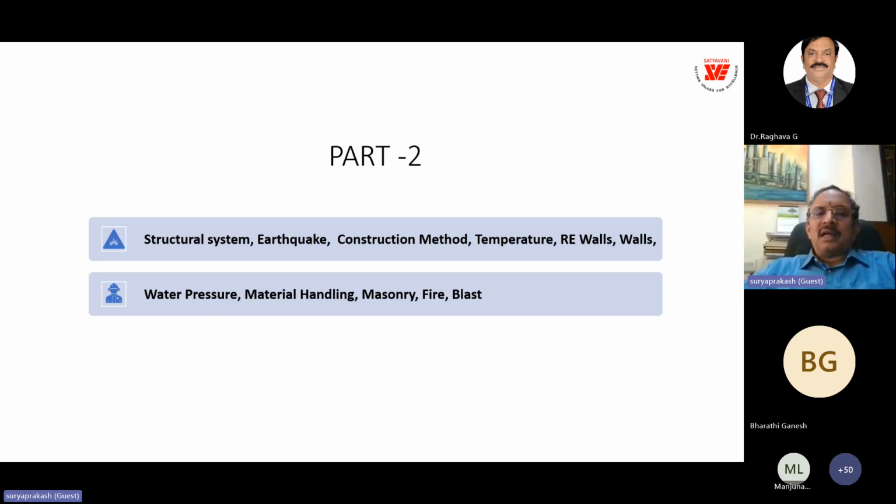Because of that, the absorption reduces and the runoff coefficient will be high, so there will be quick runoff. Normally we would have designed the sewers considering the runoff coefficient of about 50 or 30 years back, but that is no longer valid, and we have to retrofit even the sewer systems considering the present runoff coefficient. That's exactly what happened in one of our projects.